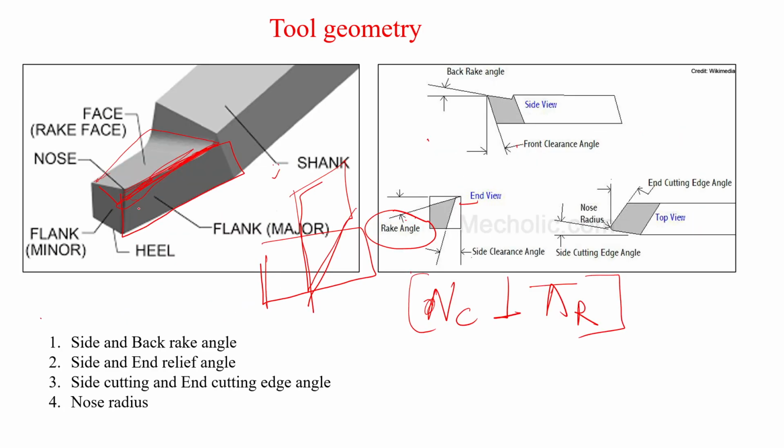So you can see some plane is this, which is passing through this. The difference between that plane and this one is an angle, because this flank surface is not straight, it is tilted, and that plane is vertical. So it will make some angle. This is called gamma or delta, whatever you say, the clearance angle. Similarly, when you measure along the x plane, it is called the side clearance angle, and when you measure along the y plane, it is called the back clearance angle. So this is called the clearance angle. Have you understood? Yes. Okay.